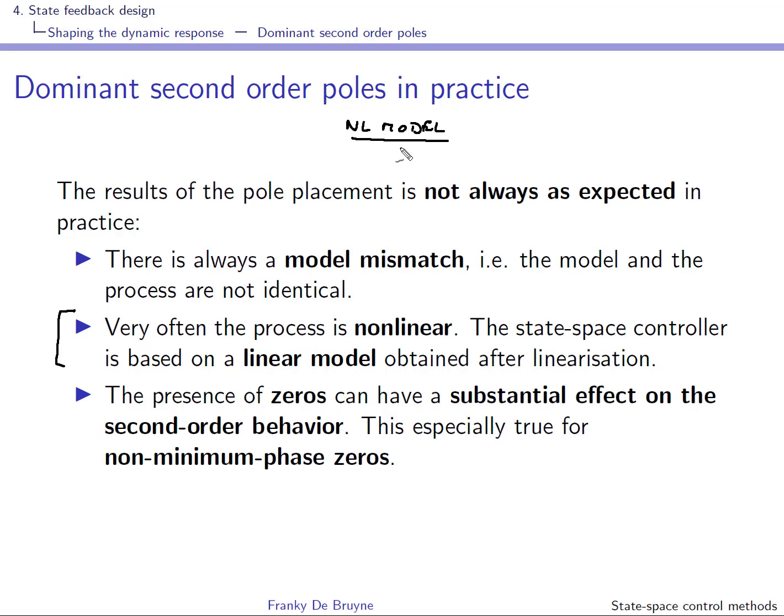So you should check all your designs, controller designs and observer designs, on the non-linear model so that you can see the effects of the non-linearities. Remember that you've based your design on linearization, and you should also take into account the effects, for instance, of saturation.